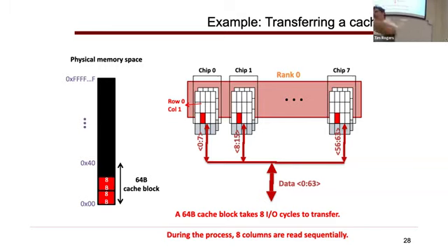So the clock goes up and down. You could choose to read either just on the rising edge or just on the falling edge or on both. If you read on both, then you basically are doubling the frequency. So yes, the data rate, if you're doing dual data rate and reading on both sides of the clock, is going to be double whatever the clock frequency is. I'm sort of abstracting that away and assuming that this is as fast as you can read stuff out.